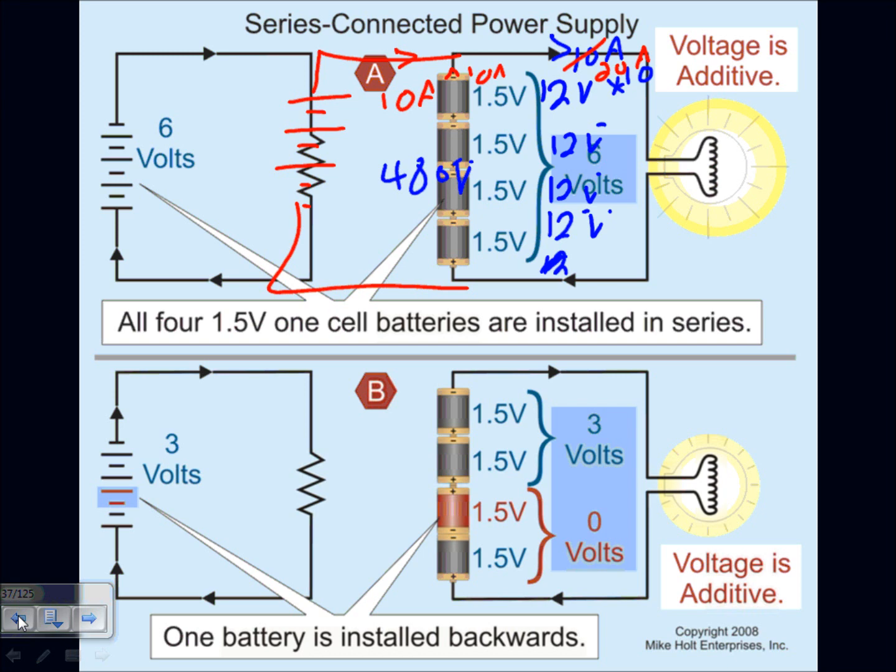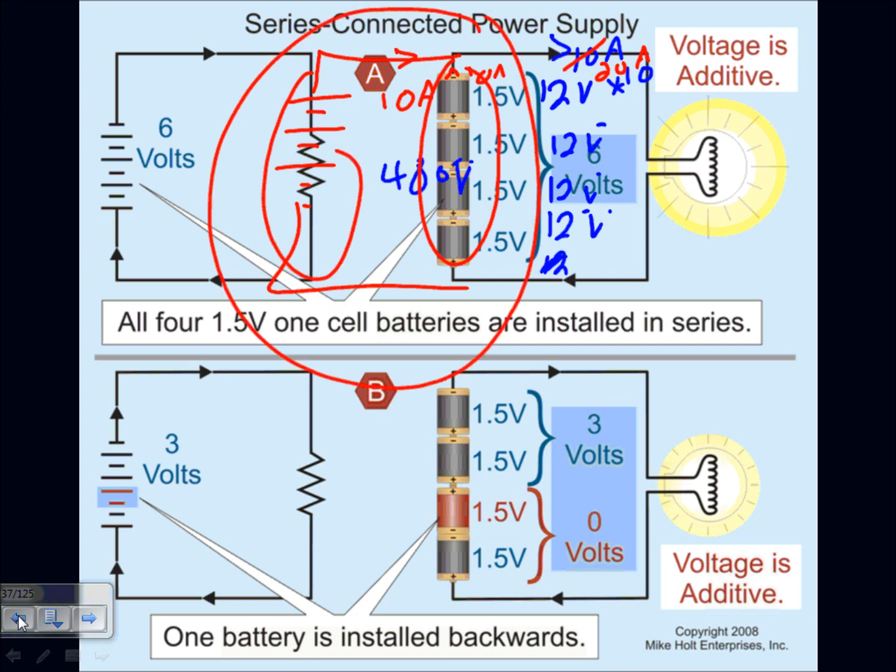Add another string, and a fourth string, and a fifth, and so forth. So this concept: putting batteries in series and then paralleling the strings. By the way, this is series, and this is series, and together we put the two strings in parallel. Can you guys see that concept? I return to this concept when you go to the commercial side too.